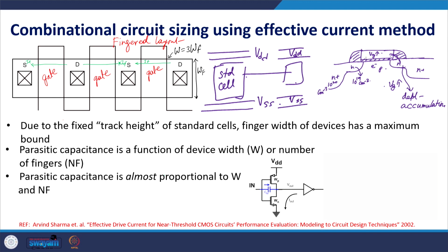Now, these 3 currents would add up at the source and drain, isn't it? So, 3 times the current of each finger would be the current of the device, ideally. Why am I saying ideally? Because of narrow width and inverse narrow width effects. You would have non-idealities: narrow width effect, inverse narrow width effect, well proximity effect, mechanical stress. These would all be layout dependent effects. But if for the present we ignore them, then we would say that the current of the device ID is 3 times the current of each finger.